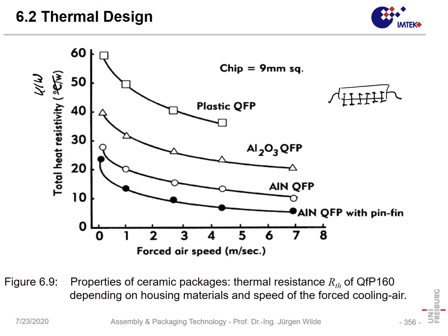So that's the QFP we have, and if it has pin fins, it just has such a structure on top, which can increase the surface area, and in that way the heat is dissipated to the air. So the materials were, what we can see here.